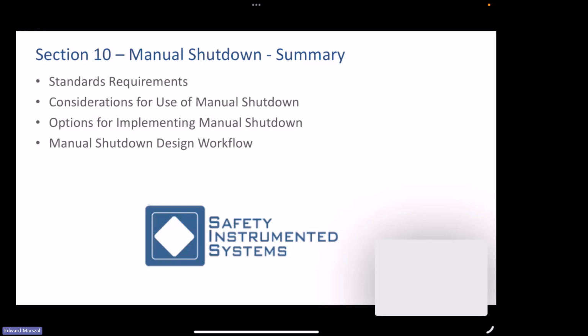I assume that you've written that down, Chris. But that's my recommendation for test intervals for manually activated valves, because at the end of the day, they are part of an IPL. That IPL has a PFD target associated with it. Next question.